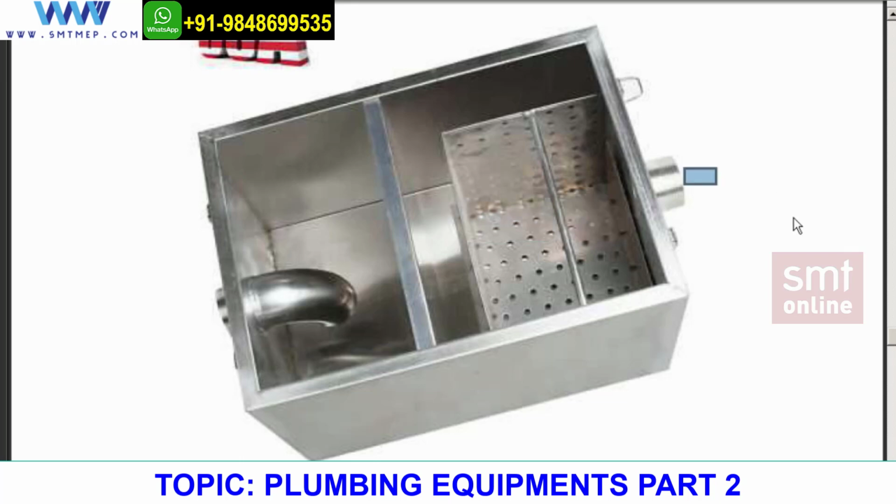Now this water can be used if there is a scarcity of water. So this water will be sent to the utility area where they'll be treating it at least, because again we'll be getting some sort of particles for sure. So this line will be going back to the utility area, and they'll be processing it again, filtering it, and sending it to one tank, and that tank will be connected to the WC flushing purpose. So I could not use this for the laboratories and all this, but this can be used for the flushing purpose for the WCs.